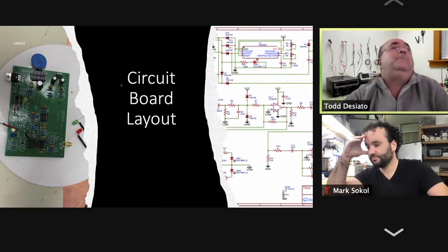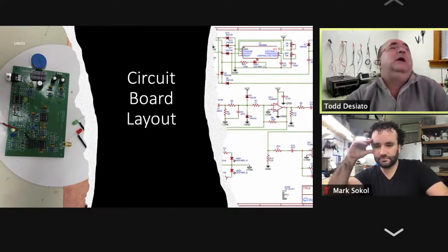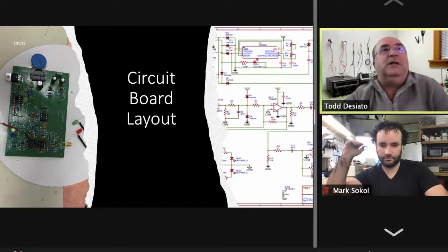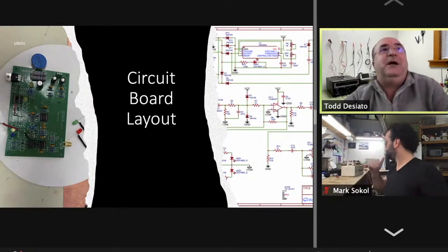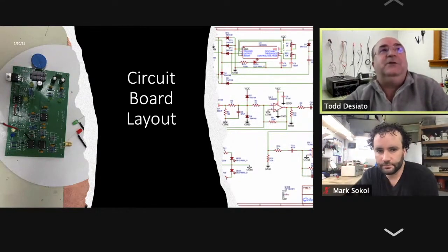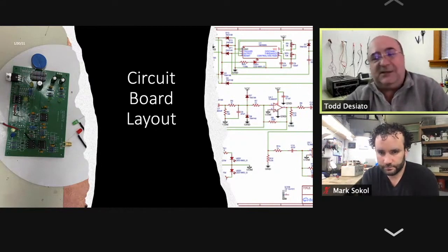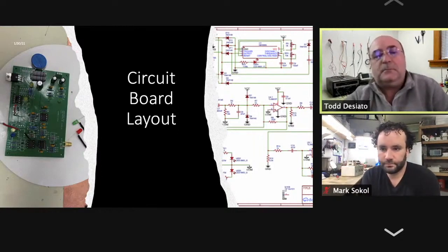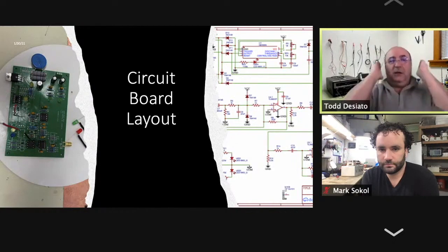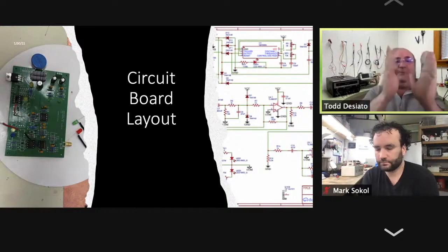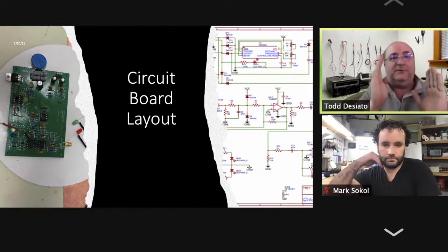And then that coil hooks over here to the board, and the MOSFET is used to charge the coil to polarize the water. Then when the coil lets go, the voltage is clamped by this metal oxide varistor and drained very quickly by these resistors. So it's overdamped, so I don't have any oscillation. I don't let the voltage reverse or the current reverse, because all I want to do is align the protons along the coil and then let them relax back to the Helmholtz coil field.